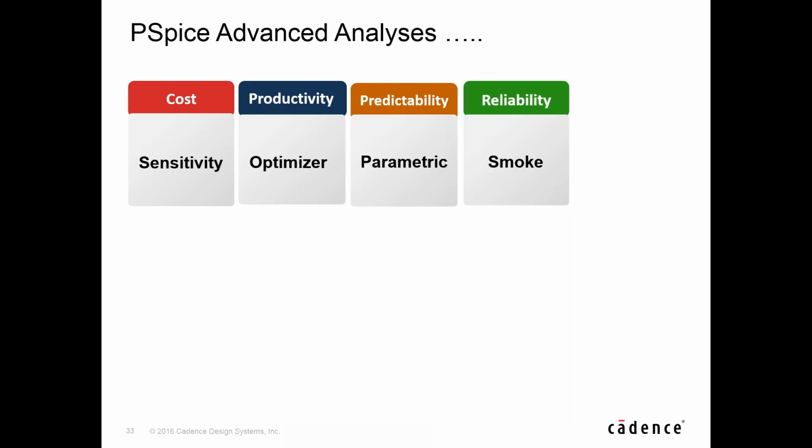Reliability in terms of smoke. There may be things like power dissipation, junction temperature, and collector-base voltages in your design that, if you do not model these things and take them into account, you may have what could be a functional circuit that can simulate, but the real physical device model could fail because you could be violating or pushing it beyond its limits.